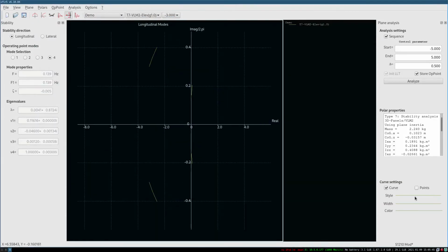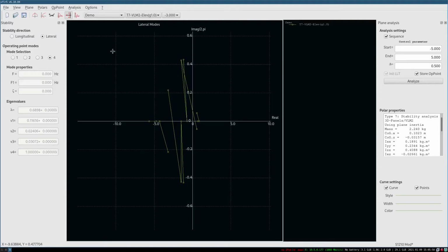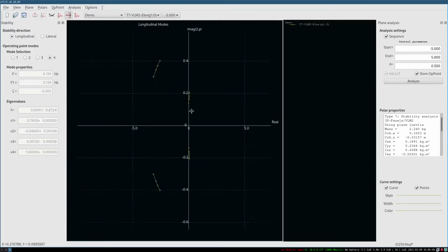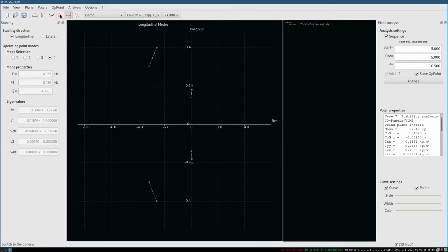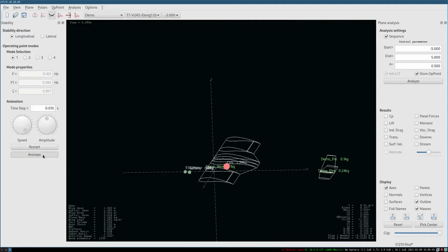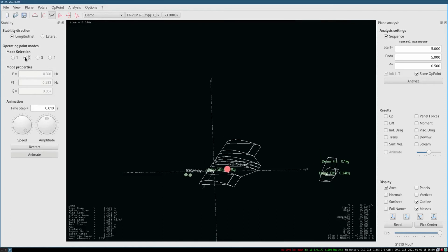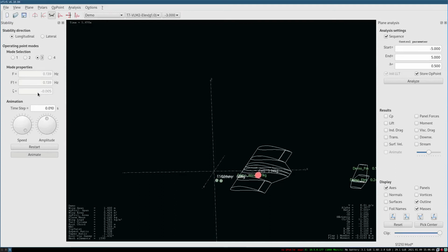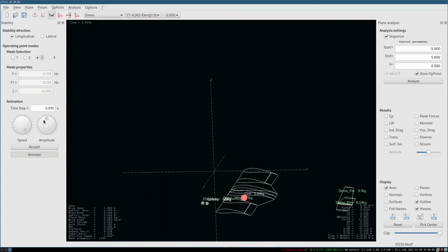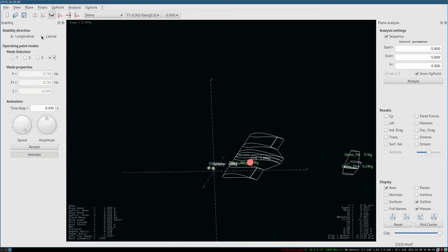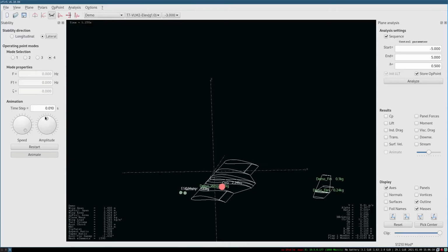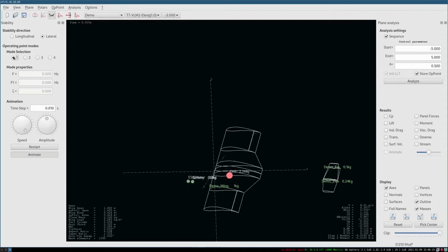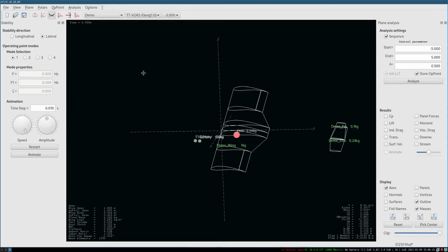Okay, so having a look at our root locus plots, we have actually made things worse. This is highly interesting, and I'm not even sure how we've ended up with two different sets of modes. What the heck? That one's fine. That one's fine. Dutch roll, damping factor is negative. That would generally mean it's getting worse. That's getting worse. That's fine, that's fine, that's fine. Okay.